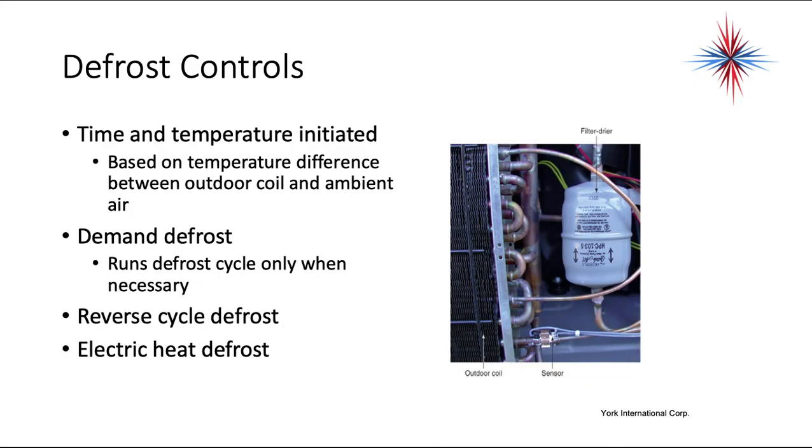Defrost is important. Okay, the outdoor coil can sometimes be running below freezing. If it's running below freezing because of low outdoor temperatures, frost will start to build up on the coil. You want to make sure that the system melts that ice off of that outdoor coil. That's why we go into defrost. Time and temperature initiated defrost is based on the temperature difference between the outdoor coil and ambient air. Demand defrost runs only when necessary. In other words, it senses if there's ice on the coil.